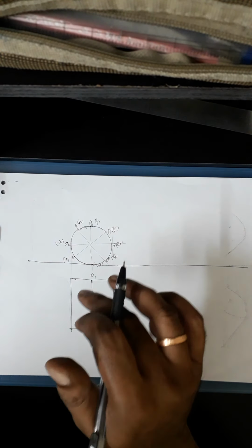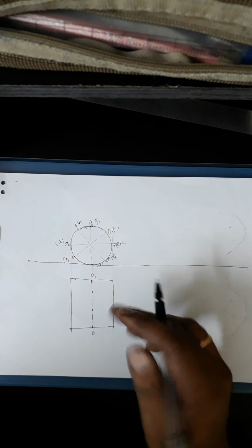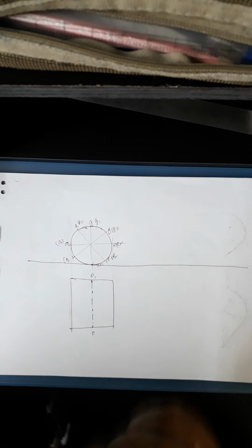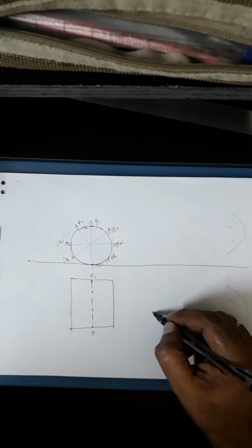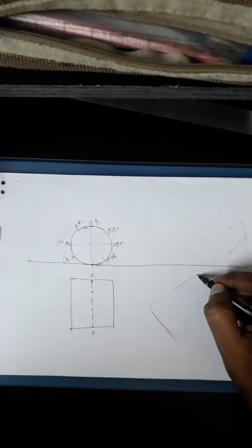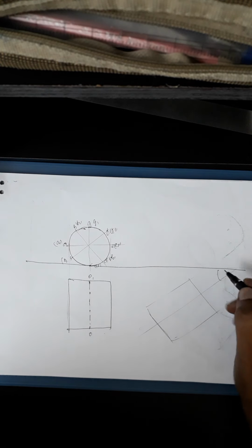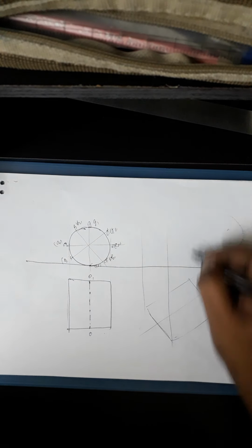Only the generator; only that type of problem will be given, because there's no edge on the surface. Even if it is resting on the surface, it will rest on only a line, that is the generator. So they'll say it's resting on a generator, then you have to redraw this in this position, giving the inclination as it will be given with respect to VP. Say this is given 30 degrees, so project all this.